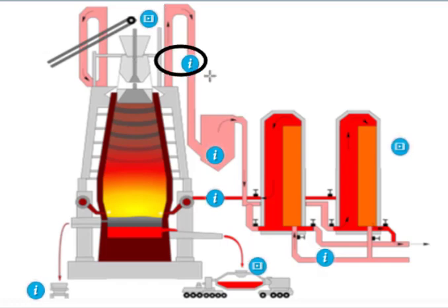This is called the downcomer. The blast furnace gas here is really hot, and it contains a large amount of fine particles to remove, and it comes out here. To remove these fine particles, we use this downcomer, which is used as a dust catcher and also a wet cleaning system. Okay, let's go ahead.